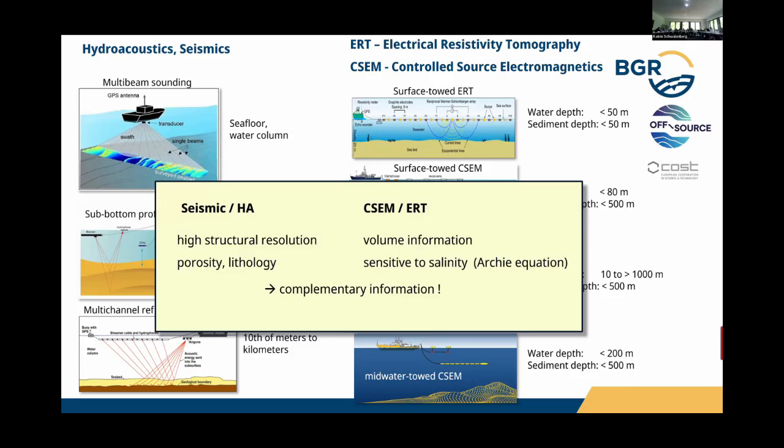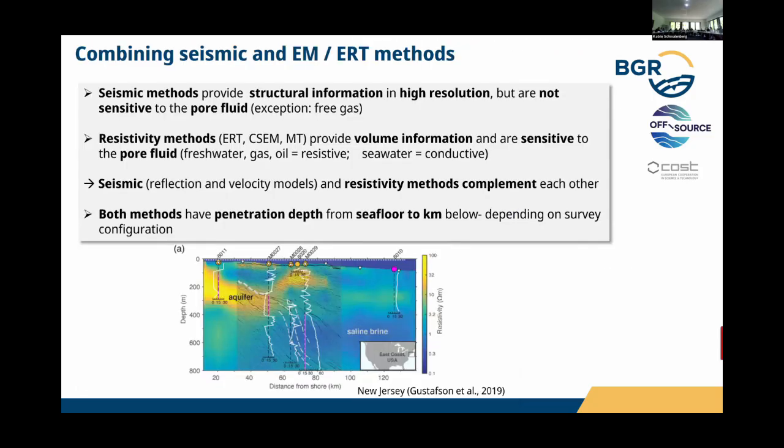Bring them together, so both methods gain knowledge from each other. Again, hydroacoustic methods provide structural information in high resolution, but are not sensitive to pore water. Resistivity methods provide volume information, but you see these blobby images. Be aware of what you can interpret and what not. And both methods can be adapted to reach a wide range of penetration depths and water depths.